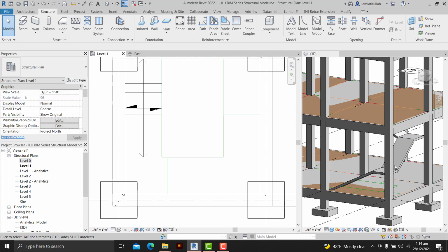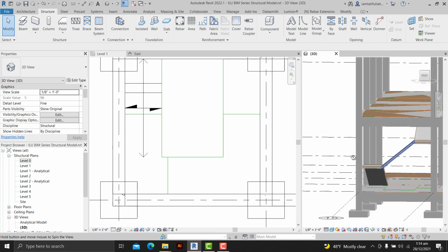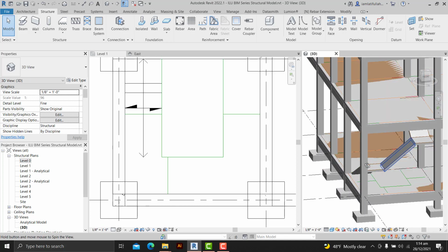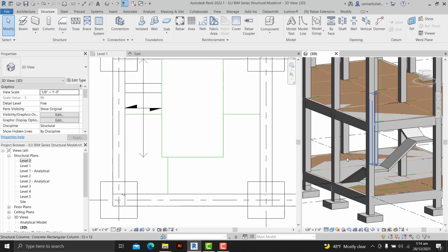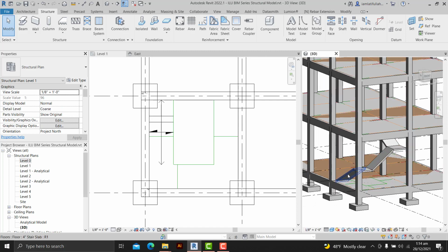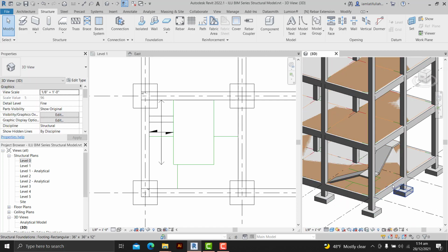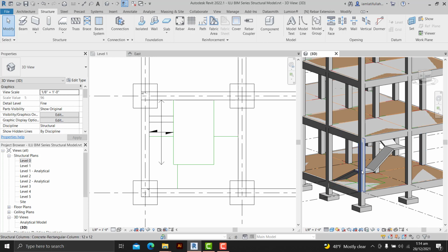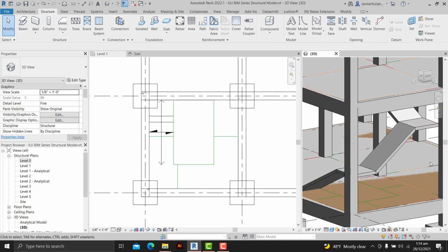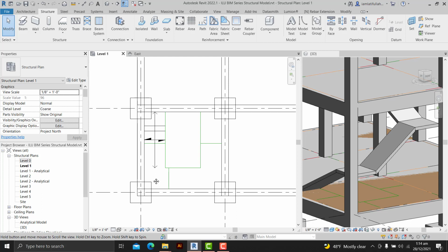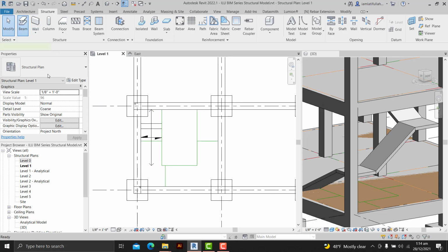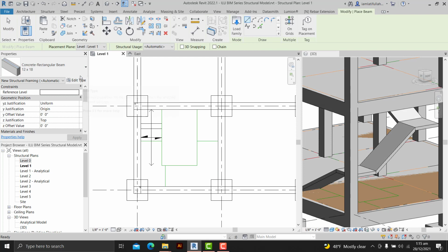Okay, I think it is fine like this. So now if you want to add a beam here to support these spans, actually, so a beam here and a beam here, you can add that too. So for that you will have to go to the beam, and now we have our 12 cross 18 inch beam here, so we can add a smaller beam here.